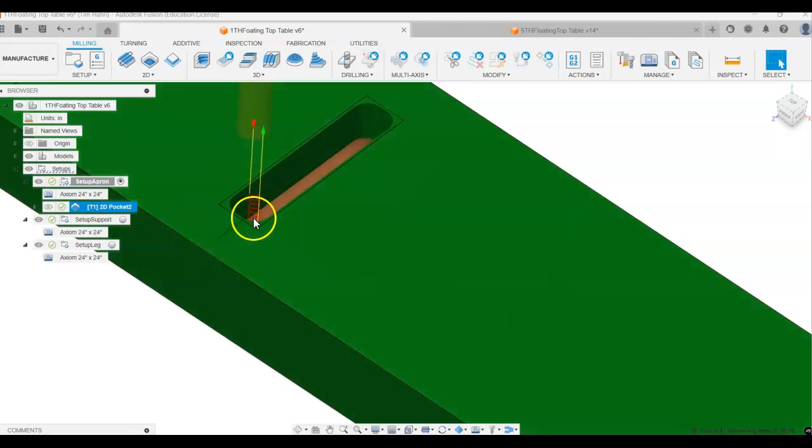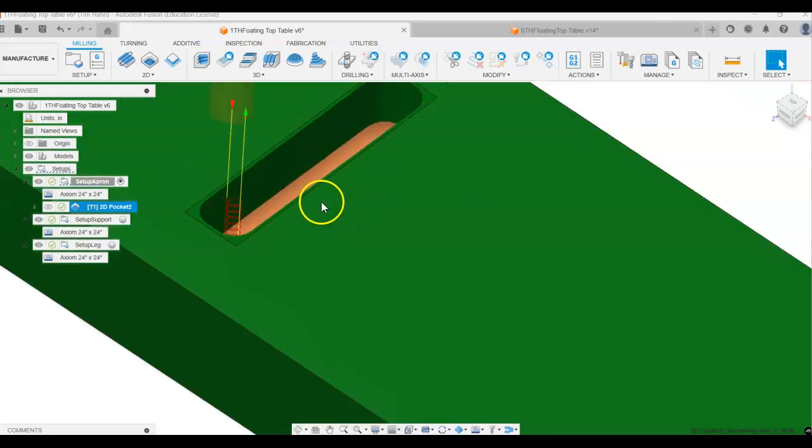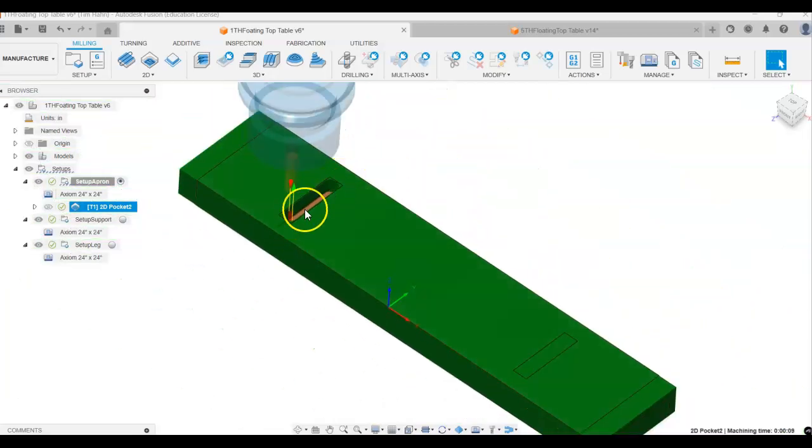All right, this is our first toolpath. This is called a roughing toolpath. So we got it close, but the bit really kind of wiggles when it chatters through here really deep. So as that bit's wiggling like that, it causes a rough edge. So it's a roughing toolpath. And this is also the toolpath on the left